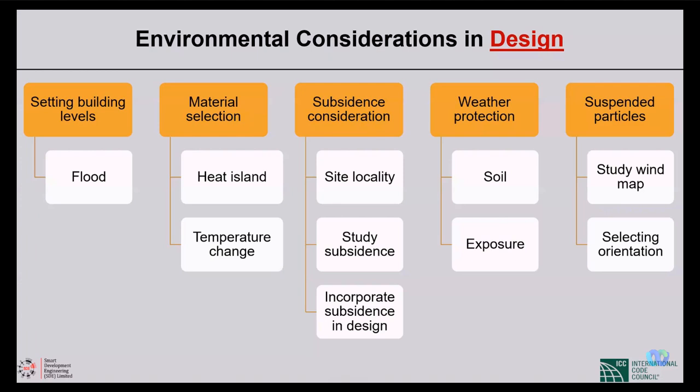What are the things we need to understand at the time of the design, what the engineers need to look at. So first in setting building levels, what you have to do is set the building levels and design levels. For example, this is the plinth level, this is the formation levels, like that. How it can be done, we have to understand the flooding and design level of your road top elevations. This you need to know.